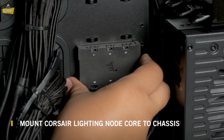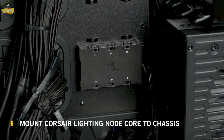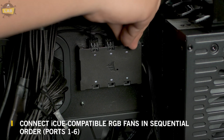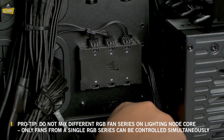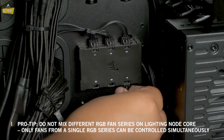To install a Lighting Node Core, simply mount the unit to an open location in your case using the provided double-sided tape. Install your fans in your case and plug them into the Lighting Node Core in sequential order. It's important to keep fan order in mind because channel-wide animations begin with fan 1 and proceed through fan 6. If you skip a port on the Lighting Node Core, all fans after the open port will not be able to communicate to the controller.